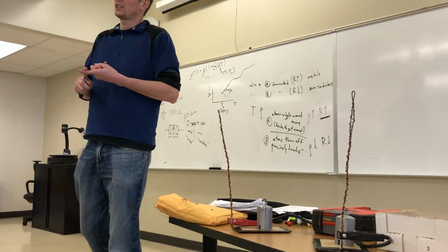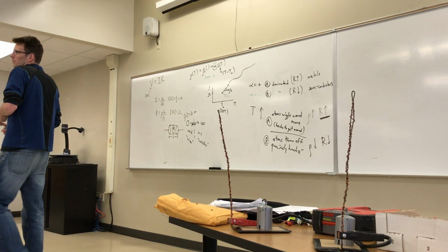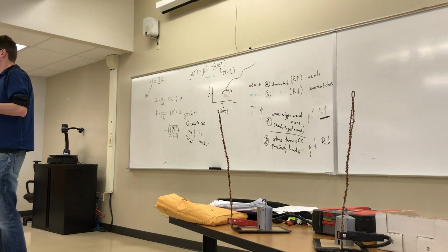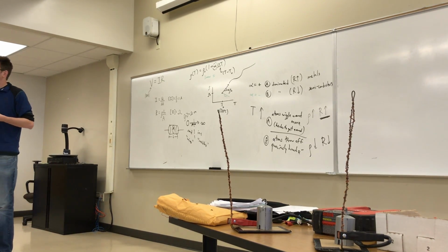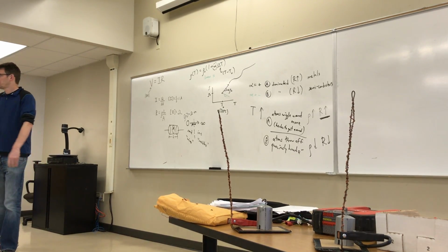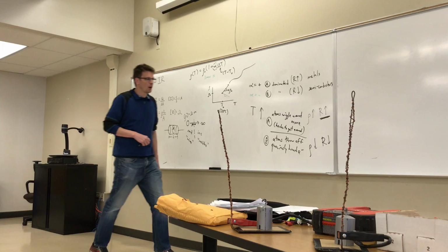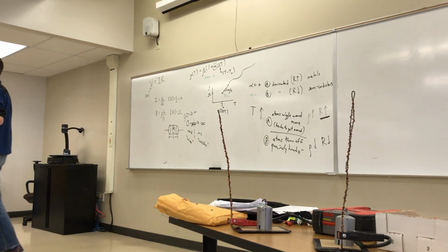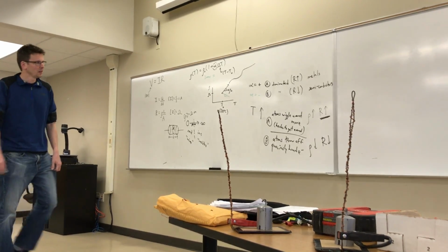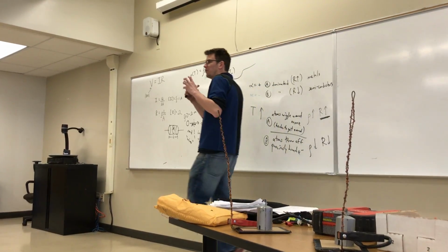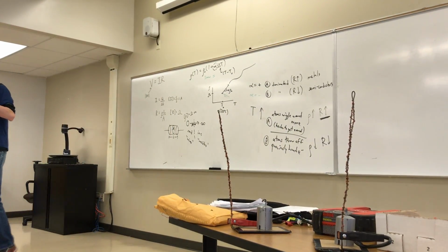So, silicon, germanium, those are the two major ones. The first computer chips ever were made out of germanium, and then they decided that for other reasons they didn't do that. Now they make them out of silicon. Okay? So silicon is one of the things that has a negative temperature coefficient, and that's a good thing, because you can coax it with not too much effort. The atoms can throw off previously bound electrons, and it becomes something where electricity can flow more easily. Okay? So that's just a little bit of how you can literally modify the physical properties with heat, and you can modify the resistivity, and therefore you can modify the resistance.